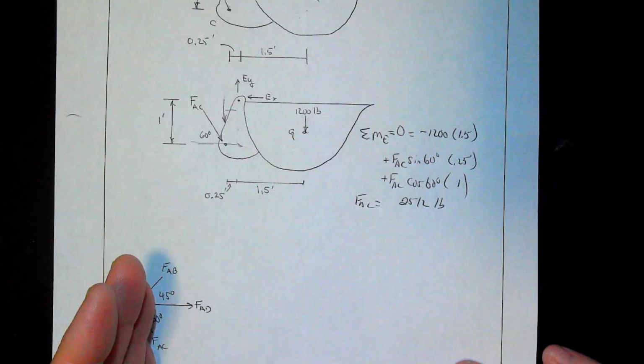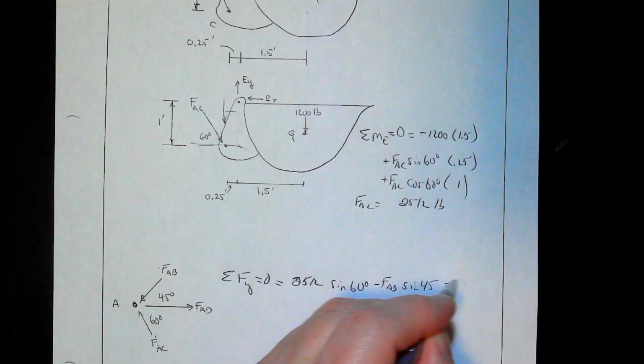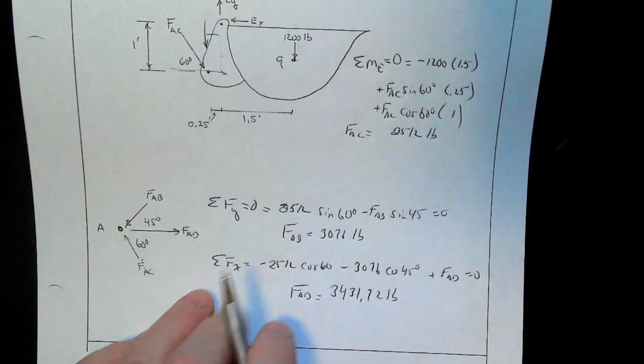And we're going to treat AD and AC as 2 force members. So their mass relative to the overall weight of everything else in here is negligible. Okay, so we have 2 force members. That means the force goes along a line AD and a line AC. So that tells us a lot about how things are oriented. All right? Okay.